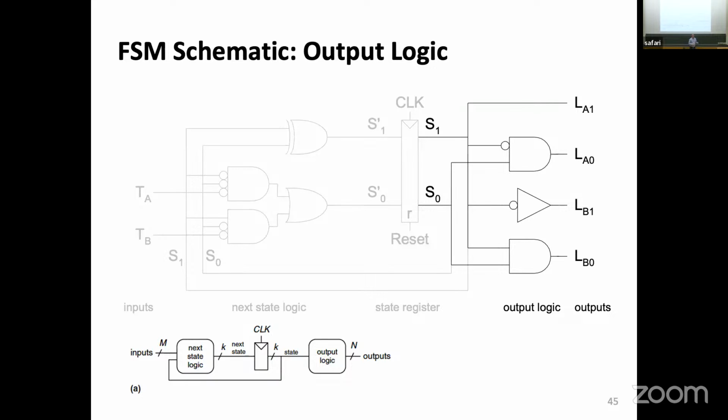Fortunately for us, it will be only in the exam that you will have to maybe solve a question like this using Karnaugh maps, equations, and things like that. For most other cases, we'll be using Verilog to describe the combinational circuit. We will write a few lines saying, hey, if this, then next state should be this. If the input is A, and our current state is this, next state should be this. We will be describing this in a behavioral way. We were talking about that before, and our life will be easier.